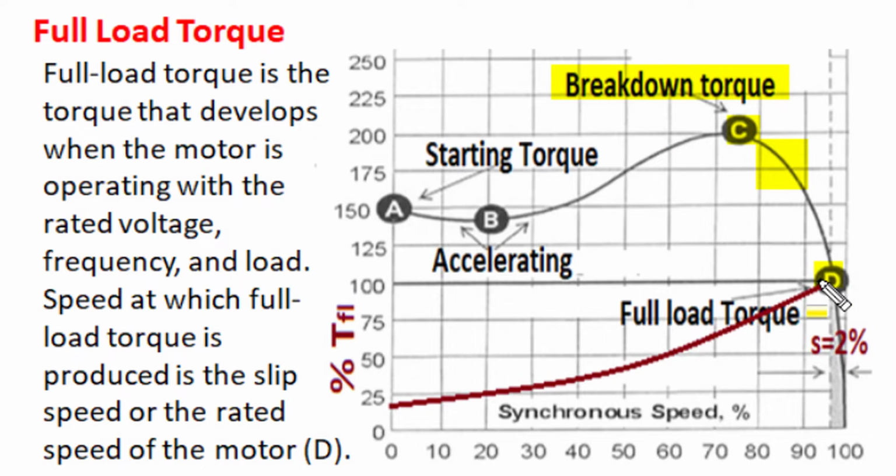Now this load position of steady state speed condition or fixed slip condition is known as full load condition, and in this full load condition the motor will run continuously in controlled temperature conditions without damaging any of its functional components, and many a time this full load condition is also the most optimum performance condition of the motor. At this load condition the motor has maximum efficiency as well as the best operating power factor.